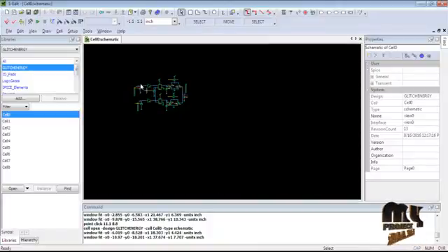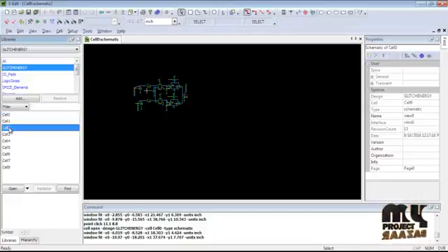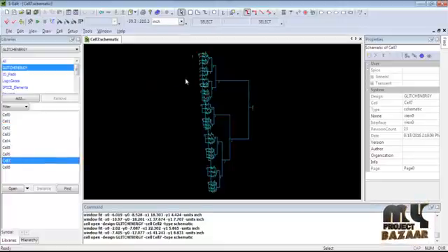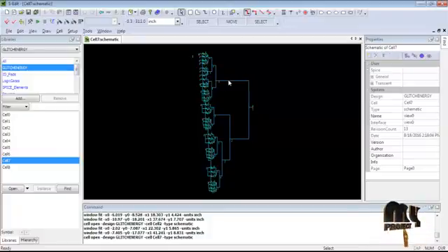In cell 0, in our product, we designed the 2-bit digital to analog conversion with compensation. This is the circuit design of digital to analog conversion for 2-bit data, and this is the circuit design for 2-bit data but without compensation. That means no compensation capacitors are connected. And next, our product's main design is here. Totally 16-bit data is given into the input buffer. That input buffer buffers the digital signal into the D flip-flop. In the D flip-flop, given the clock signal, the output will be displayed depending on the clock signals, and after that the D flip-flop output is fed into the BWCS, that means the binary weighted current switches current steering digital to analog converter block.